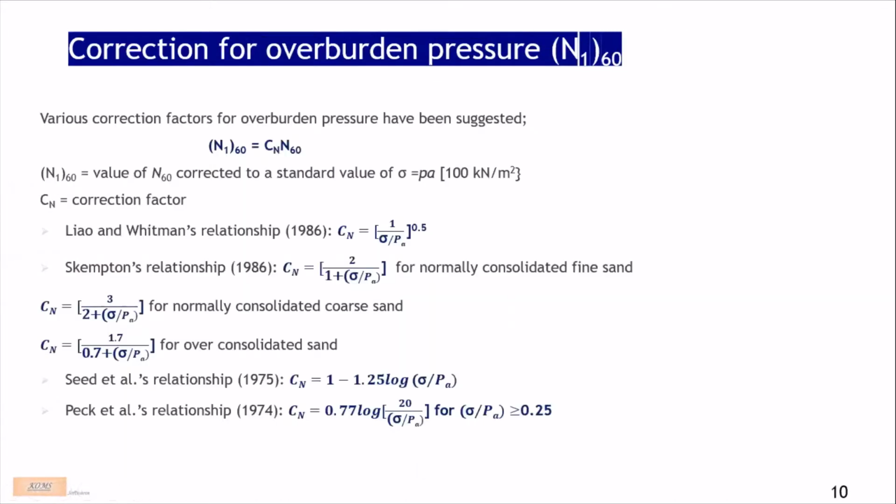So there are some things to note. From several investigations, it has been proven that the N value, that's the penetration resistance, is dependent on overburden pressure.